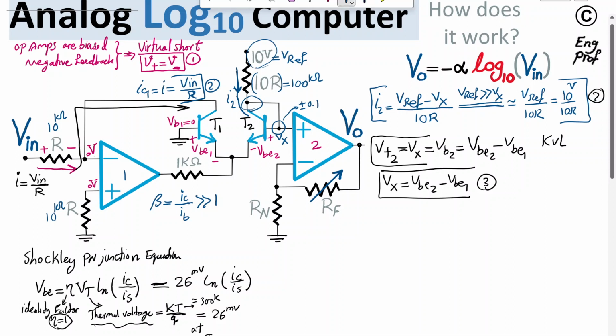This equation is what I actually needed, which defines the base-emitter voltage as a function of the collector current of the transistor. One important reminder: you can see that Vt is linearly proportional to the absolute temperature in Kelvin of the junction. Is is the most dangerous one. This one is exponentially dependent on temperature, so Is is exponentially varying.